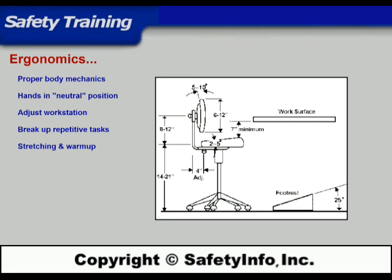Improper lifting is not the only activity that can cause stress injuries to your body. The study of proper body positioning and motion is called ergonomics. Through application of ergonomic principles, jobs, tools, and task motions are designed to minimize repetitive stress. Some of the most common ergonomic principles are keeping the hand and wrist in a neutral or handshake position. Bending the wrist weakens the grip, which causes more force to be applied to accomplish a task.